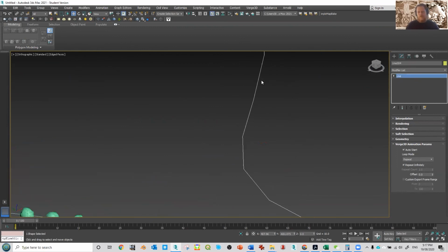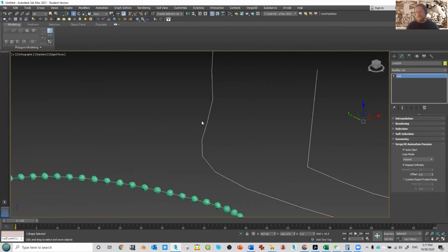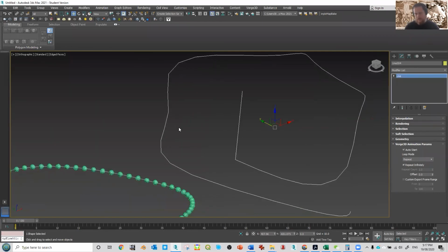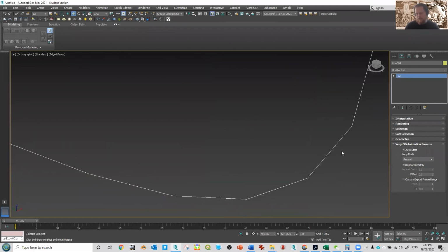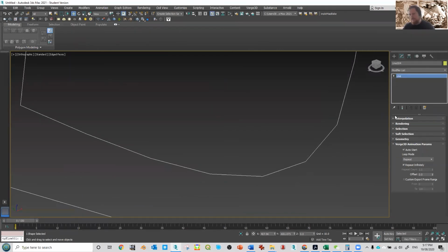What Max does, the same as when it does a sphere, is give you an approximation of a sphere. This is one of the big differences between something like Rhino, which is a NURBS modeler by default, and Max, which uses polygons primarily, as an approximation of the geometry. It's not the pure mathematics. It simplifies to display and animate more quickly. So splines will be a little bit chunky; you can see that's a curve, but to speed up the display, it facets it. Sometimes that's fine, sometimes it just looks a bit too ugly.